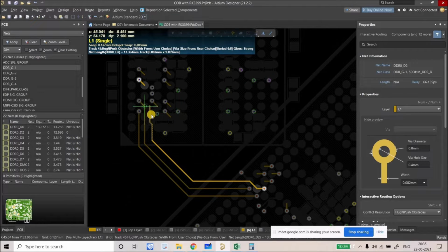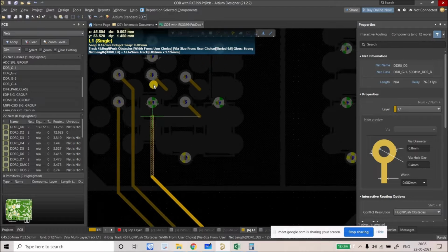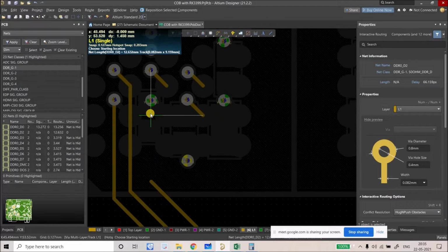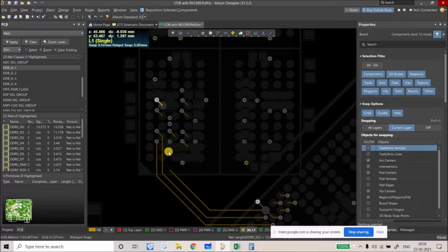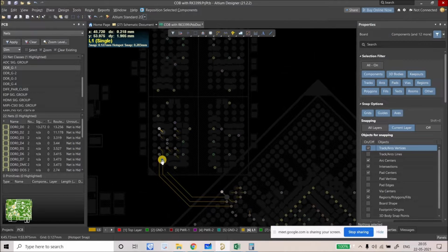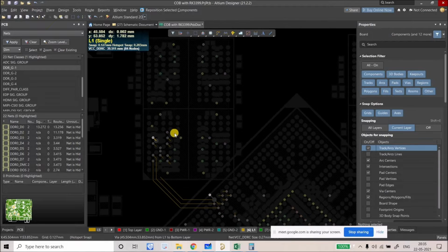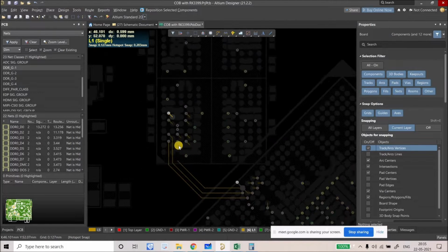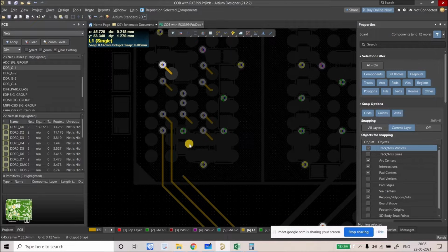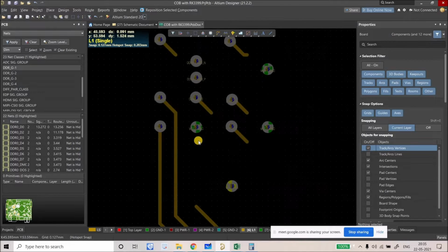All right. Now here you will see this problem, right? Because we found all the power pins before this one, you will see these will create issues during the layout of this high-speed track. But what is the priority? Which should be the best layout, the power pins or the high-speed track? Obviously the high-speed track, right? So for now we have to adjust this one.